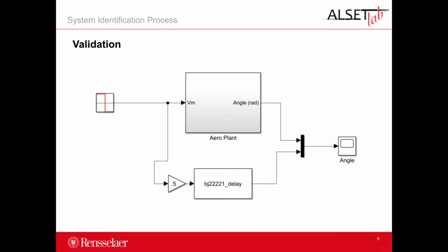So the potentially final step of system identification is to evaluate the estimated model for its adequacy. The Simulink tool pictured here was developed to quickly evaluate several estimated models. The low-frequency sine wave generator at the left of this tool feeds an input signal simultaneously to both the Quanser AERO and the estimated model.